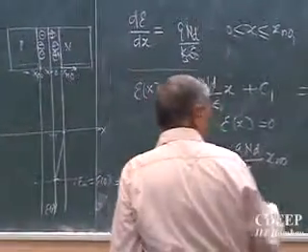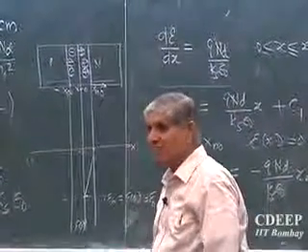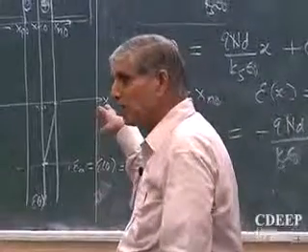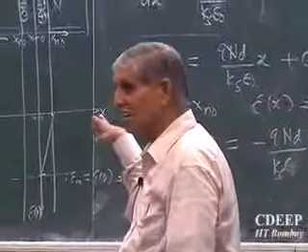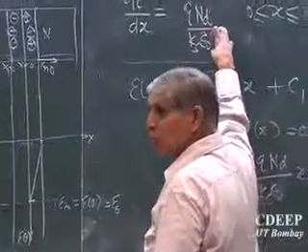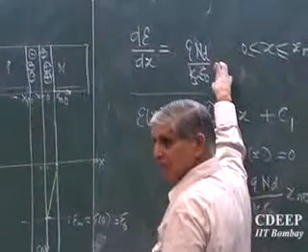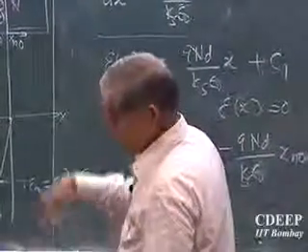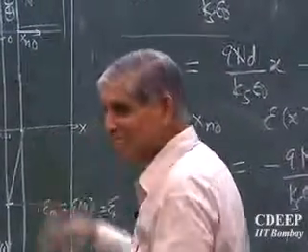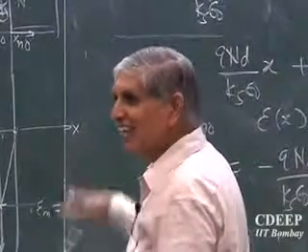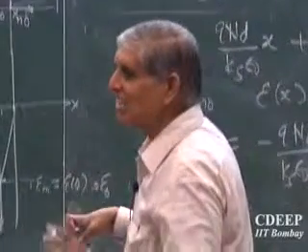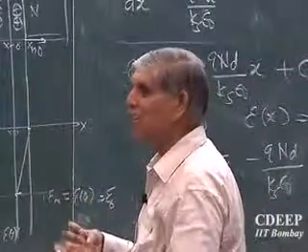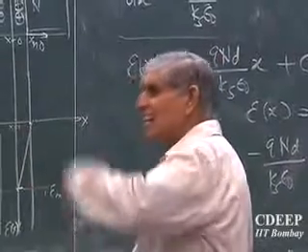Can you think now that for the other junction which I showed, like linearly graded or abrupt or something, this profile will not be linear then. Is that clear? Because this expression will have some x term appearing here. So when it has x, it can make a parabola, a hyperbola, or something else. Right now it's linear and that's what I say. Abrupt junction is simple, easy to understand. So we'll solve that. And what else will they ask you? Linearly graded, all these.